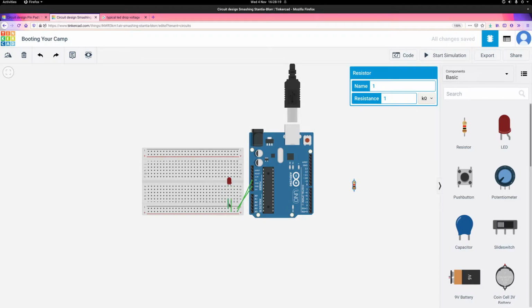So we'll connect up our resistor, and it can go either on the positive side or the negative side as long as it's in series. So we'll have to move one of these wires here to connect our resistor. I'll get rid of our negative one, grab our resistor here, rotate it sideways, and put it in like this. So now our power comes in, goes through the LED, comes out, goes through our resistor, and then I'll move that up one, and we'll take it from there down to negative voltage. Wonderful. Yep, that looks all right.